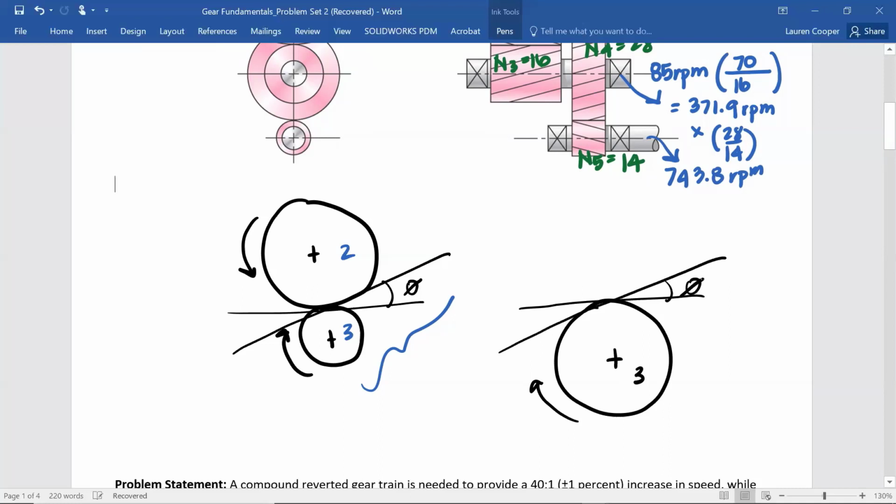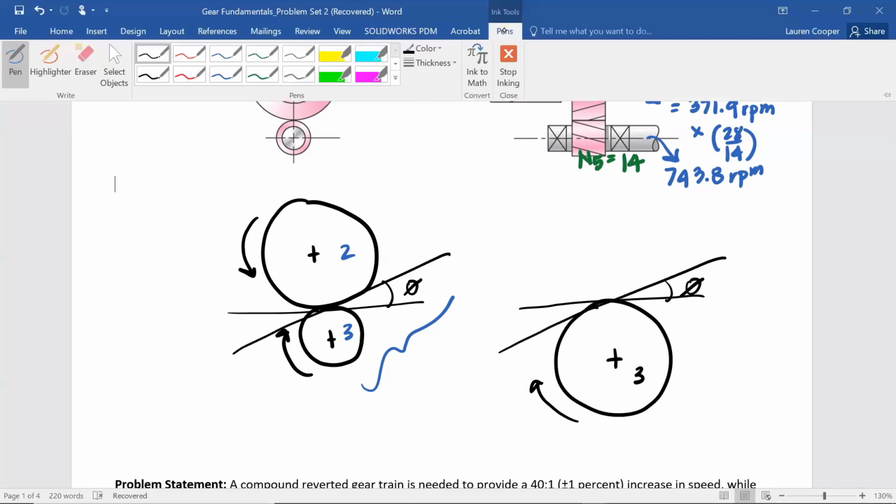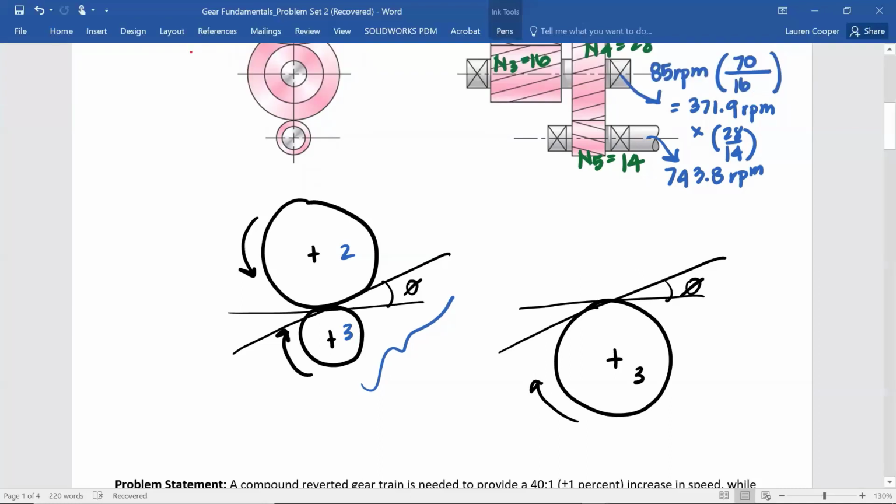So there are 3 different force components acting on gear 3. There is the total force acting on gear 3 by gear 2. So you can kind of think of it as gear 3 rotates and it kind of bumps into one of the teeth of gear 2, and gear 2 pushes back on gear 3 with this F32.